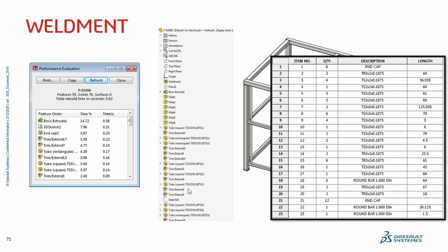Like I said, in the weldment domain you can also get the cut list, what we can call a bill of material, which is required for procurement of that data. It is fully customizable. You can add the columns that you require, like quantity, description, material. You can also customize those tables inside the weldment cut list. So please make sure you use the weldment command.